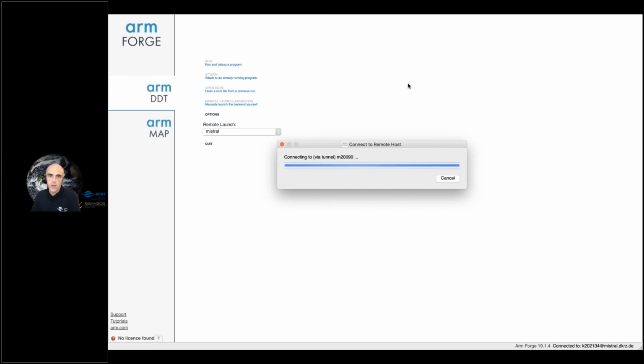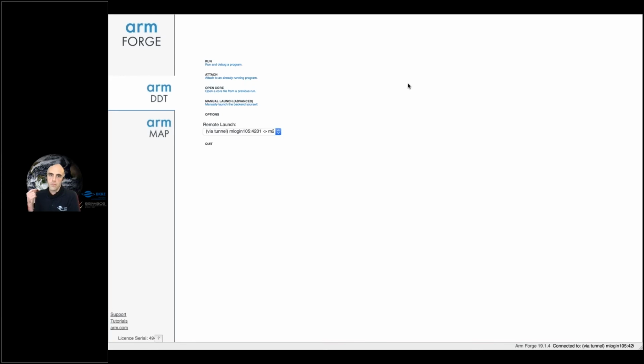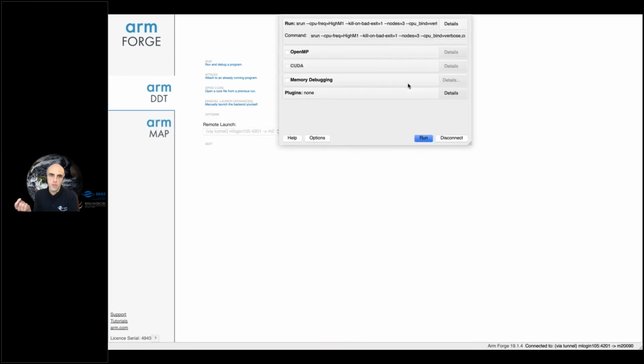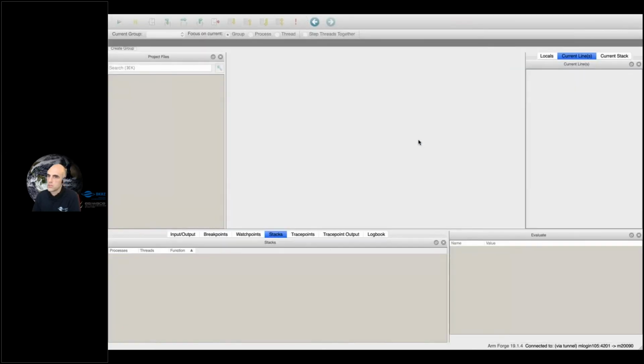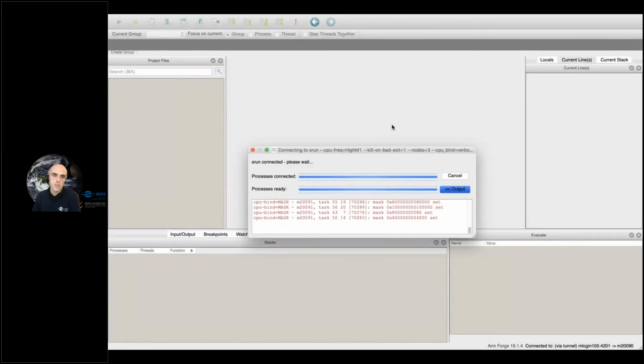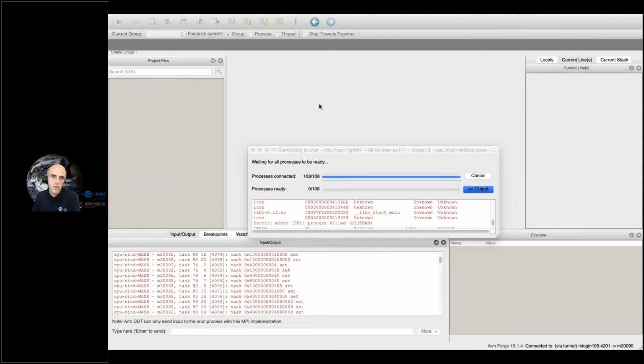So we're doing the same game again, just this time I have compiled the model without the floating point exception trapping. So it would just run over any error that doesn't fully crash it for other reasons. So a segmentation fault would still be detected, but these divide by zero things don't get detected in this setup.